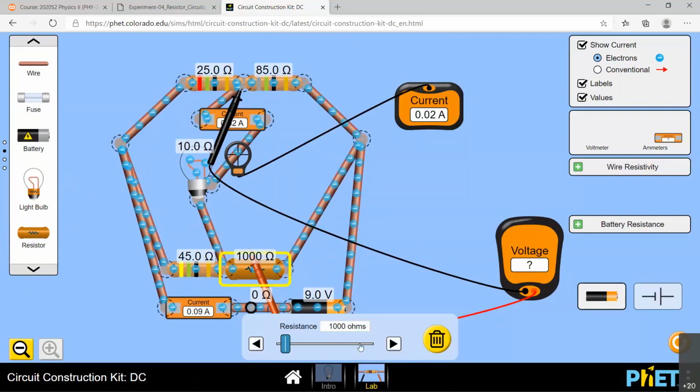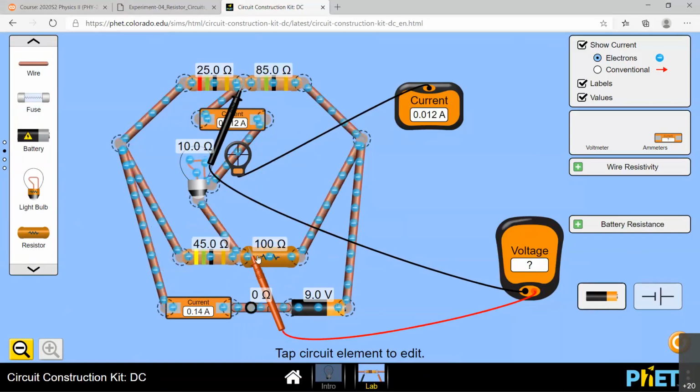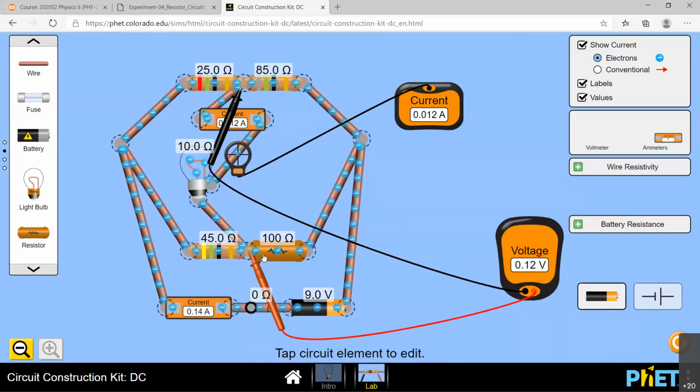With the larger resistor, I should be able to change to large numbers above 100. You have to change this resistance into a larger value, okay? On the right hand side, in the selection tool, click the down arrow, then you will get a different type of resistor. You can see the symbol is different. That resistor you can go above 100. With the previous resistor, the symbol with the 4 lines, you can't go above 100.